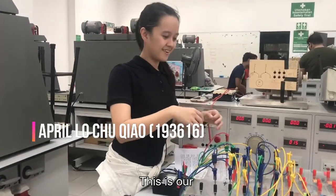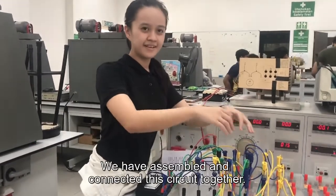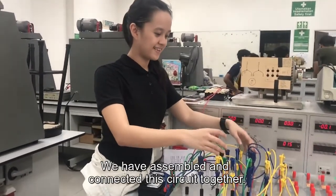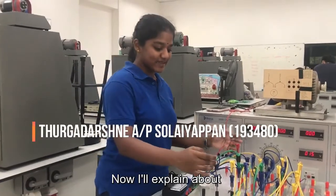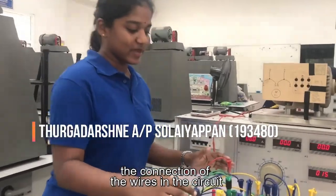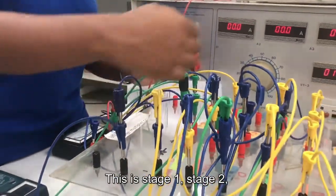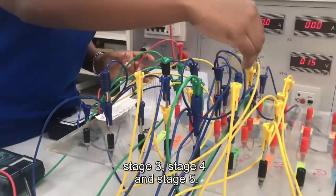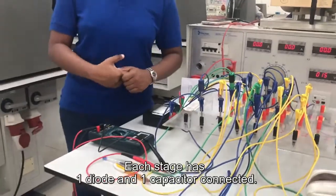This is our Cockcroft-Walton high voltage multiplier. We have assembled and connected this circuit together, and you can see the circuit here. Now I'll explain the connection of the wires in the circuit. This is the positive and negative terminal. This is stage 1, stage 2, stage 3, stage 4, and stage 5. Each stage has one diode and one capacitor connected.